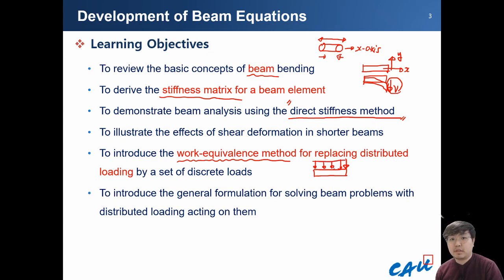This is a distributed force on the beam. Due to the distributed force, the beam will deflect, looking like this, when we have those kinds of boundary conditions. So to apply those kinds of distributed forces, we should change this force into nodal forces.